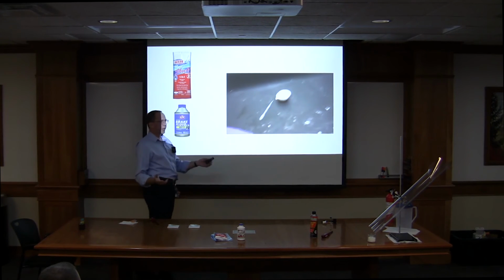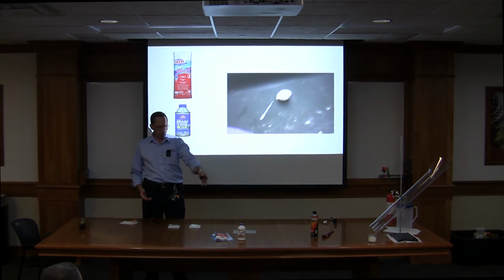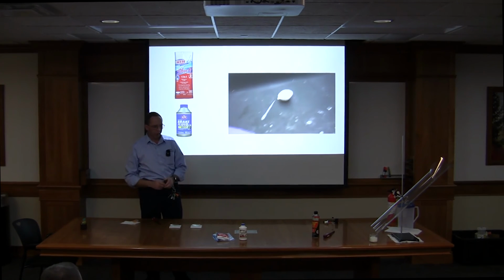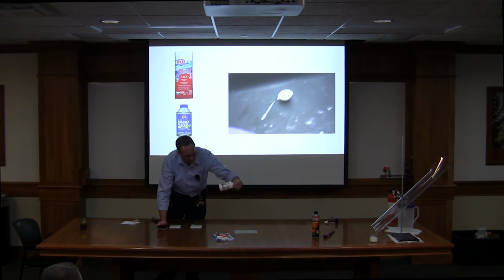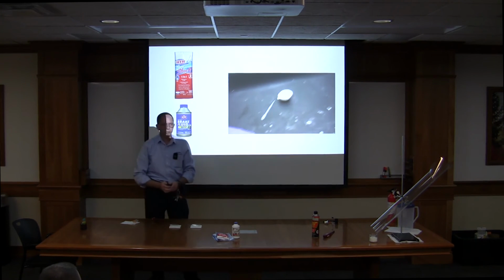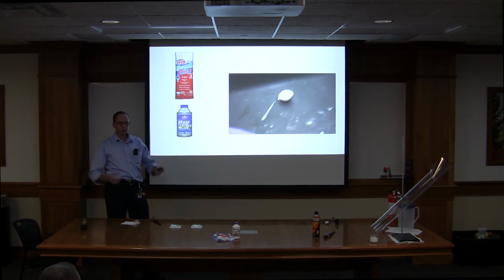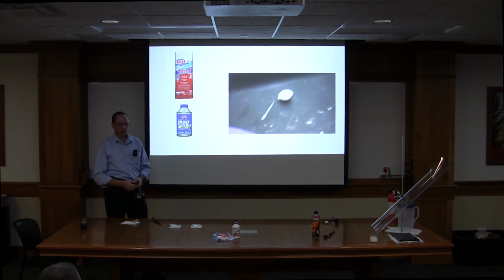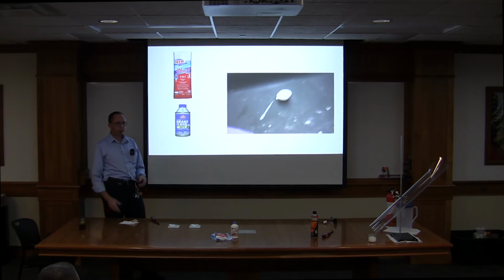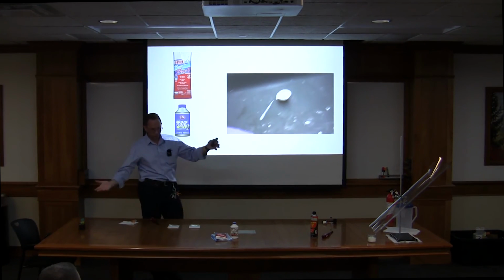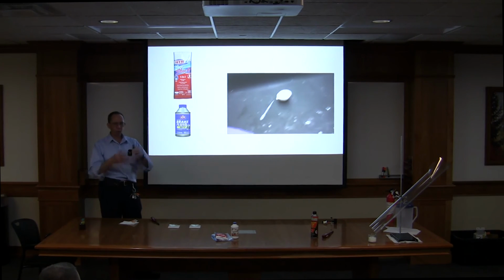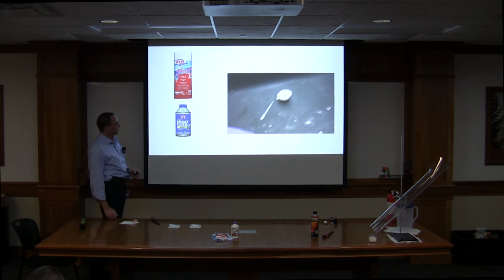Or you are here on campus somewhere and you've got these two chemicals sitting in a storage cabinet in your work area, and this is just plastic, it's high density polyethylene. It springs a little leak and some of it leaks over here and you get a reaction going. There's lots of plausible scenarios where these incompatible materials could mix and start a fire without even touching it. So it becomes very important when you've got things like acids and bases, oxidizers and organics, different classes of materials that are not compatible, make sure they're stored separately.